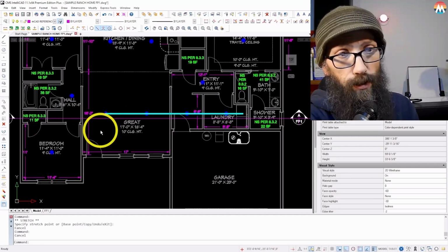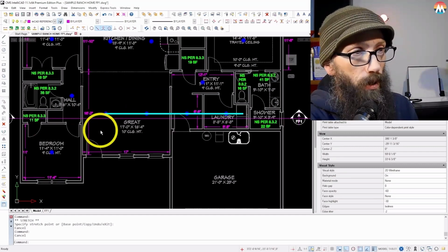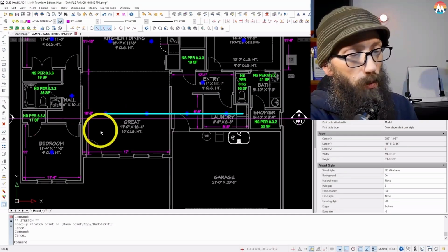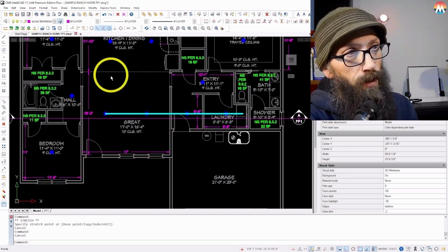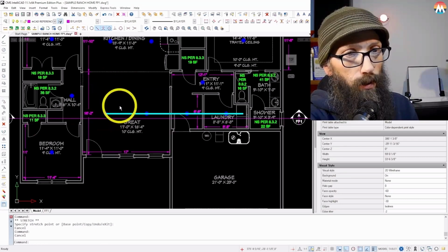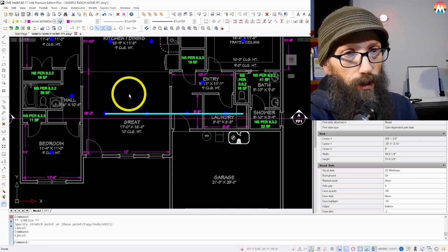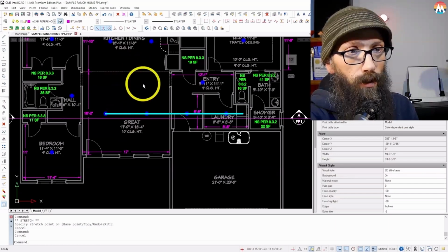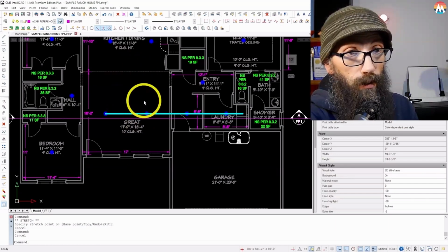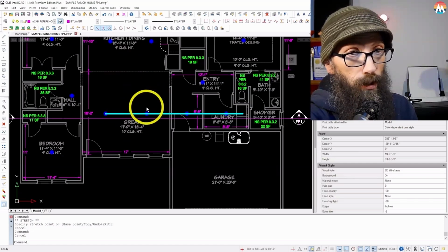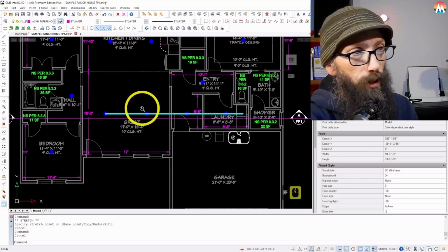There's just a way that's easier, one way or another. If this was a 2-story building, the direction that the floor joists are traveling on the second floor would be the ceiling of your first floor. So you'd want to travel between the floor joists parallel to them as much as possible to minimize drilling.